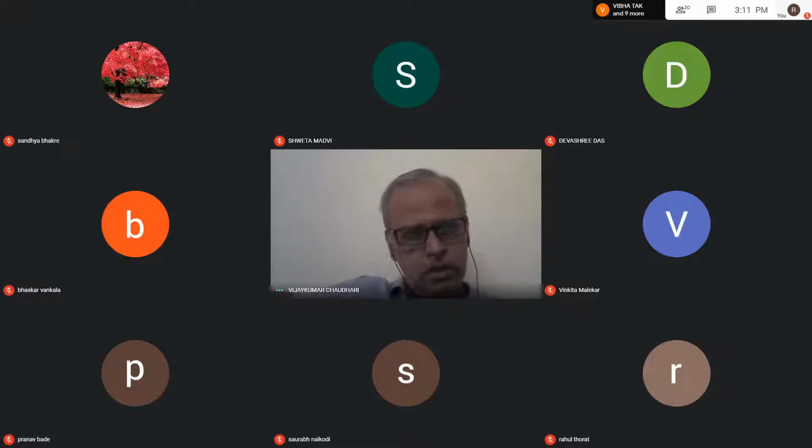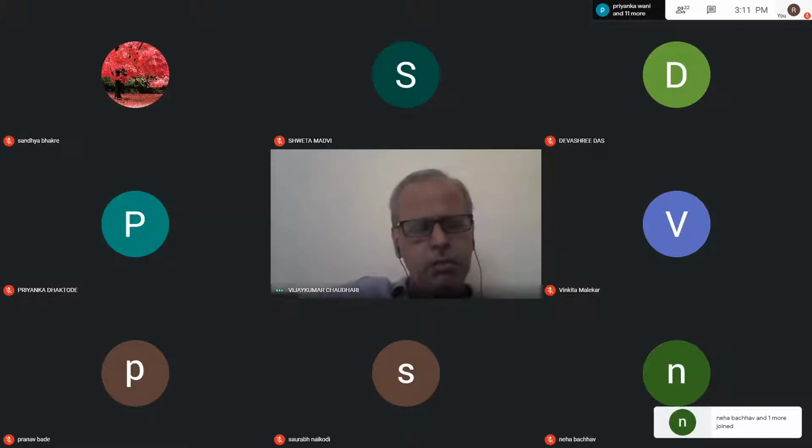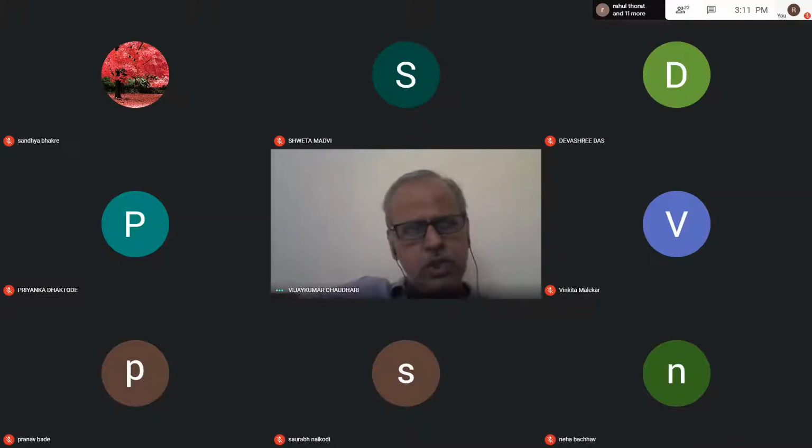And where is this difference used in industries? It is used for measurements, right? So the two inputs of the instrumentation amplifier generally come from a bridge. The bridge input comes from a sensor, which is part of one of the arms of the bridge. As the sensor parameter changes, the bridge output changes, and this change is a differential output VA minus VB. This VA minus VB is applied to the instrumentation amplifier. Do you understand this concept?